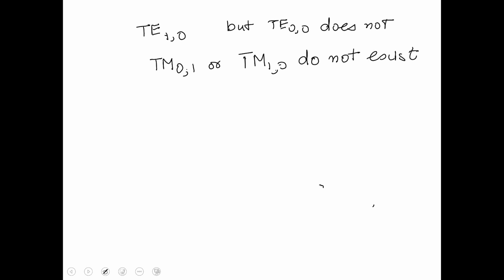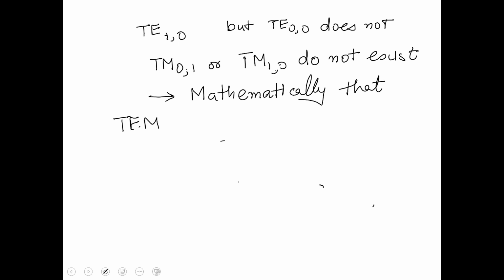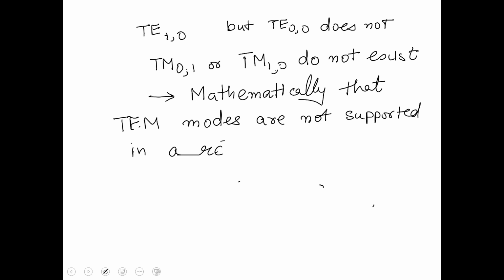And if TM10 and TM01 do not exist, TM00 will not also exist. So we have seen mathematically that TEM modes are not supported in a rectangular waveguide.